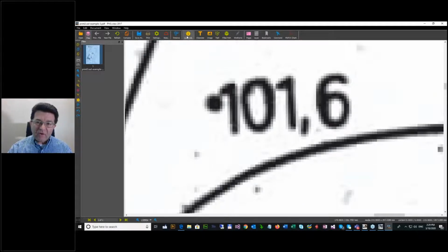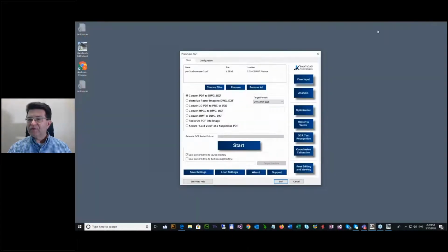And you can go here on color info and pick one pixel. For example, you can pick this one and it tells me this is a heavy white background. You see, this is the color info. Or you can pick here. I need this point and this one separated, like here, 0 and 1 have to be separated. So my threshold is this color. And you see the color is not really grayscale, but it is about 40, 41 hexadecimal.